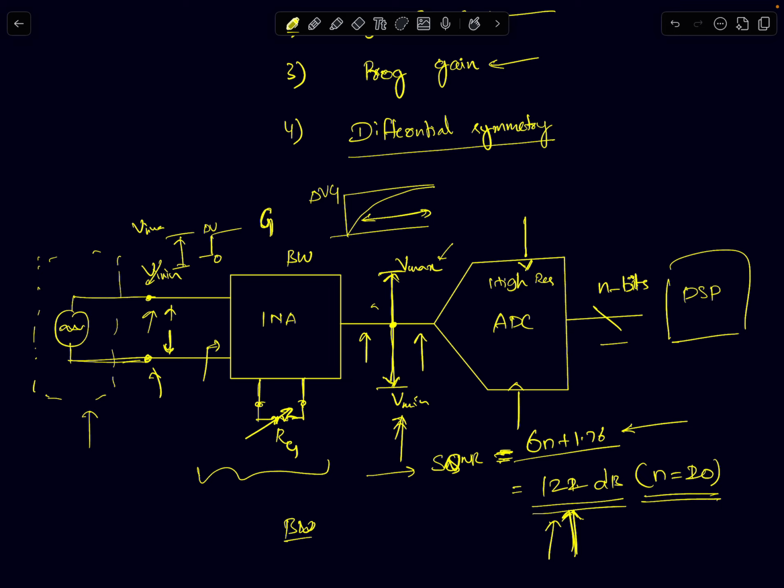So all the analysis that we did for offsets, for single-ended non-inverting and inverting amplifiers and buffers, all that will hold true here as well. So that's why I didn't discuss this separately. What I will discuss in the next lectures is CMRR, because CMRR is a very important specification. How do you achieve such high CMRRs? Okay, everything in the instrumentation amplifier will matter. So we'll see what other factors impact CMRR and how to design for it.